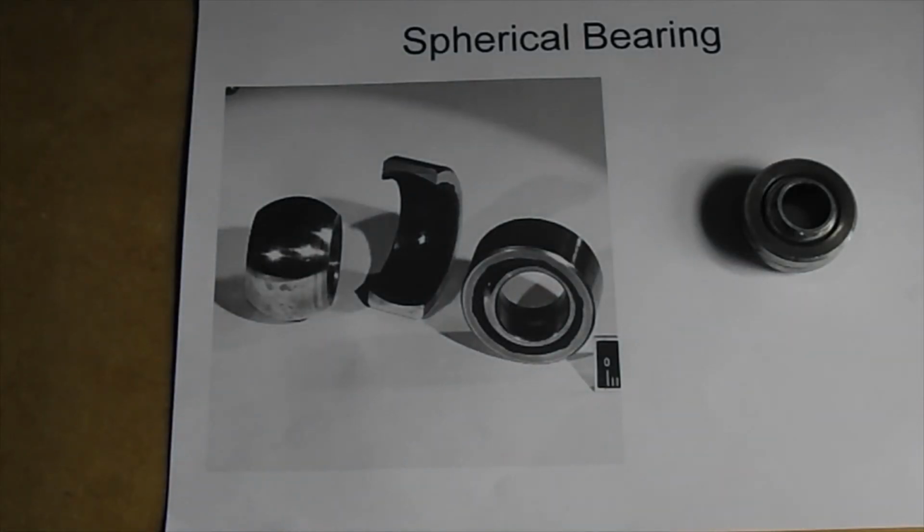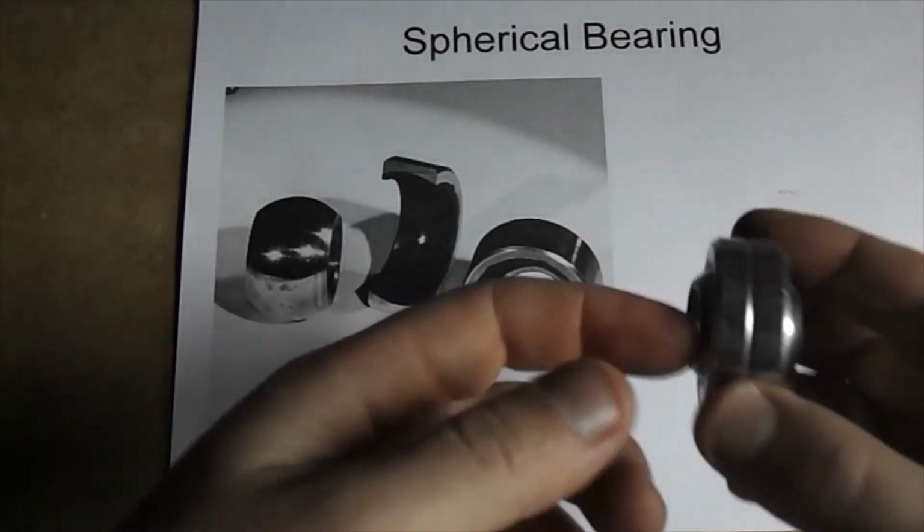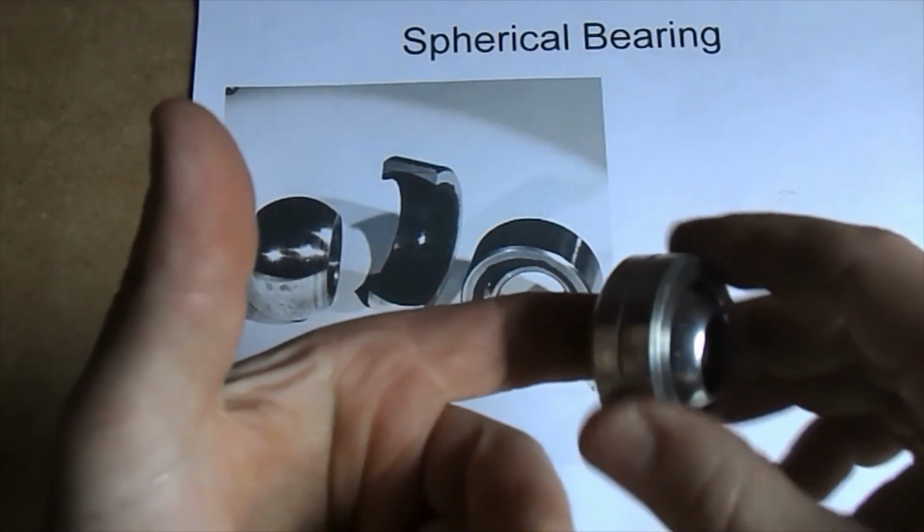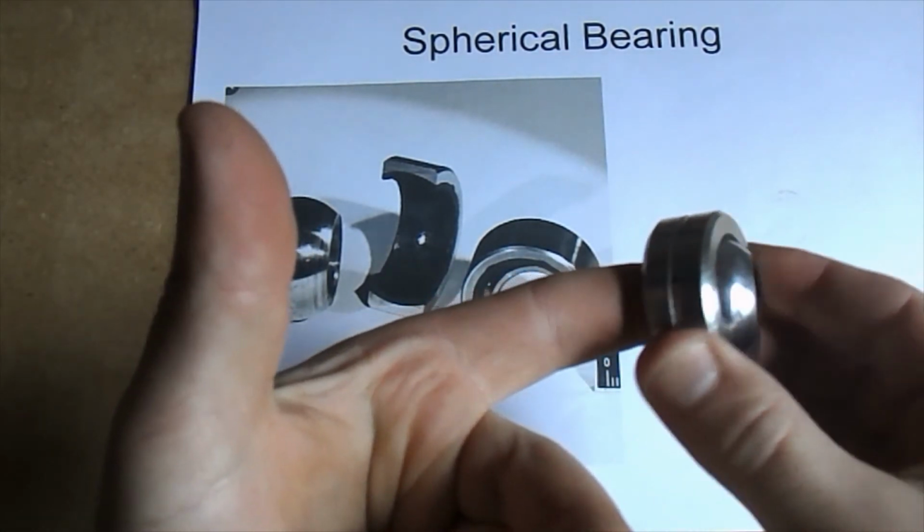Spherical bearings are used where there is movement on parts on different planes. Only small amounts of rotational movement can be accommodated. Good solution for alignment problems, applications of car steering and suspension assemblies. You see the bearing has rotation but also spherical movement.